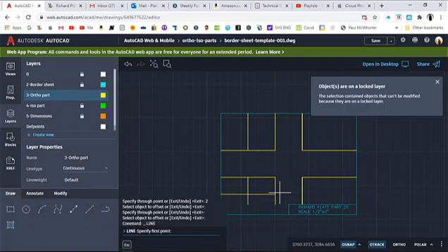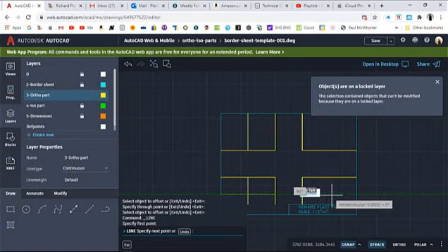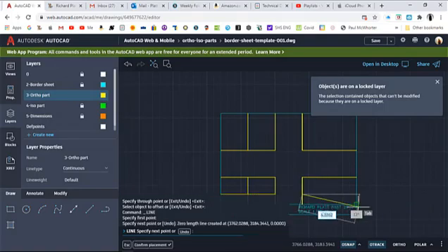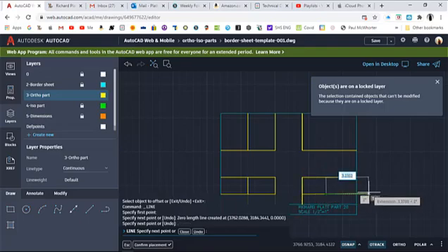And what we'll do is we'll snap onto the end of this line right here and just extend across just by touching it. And AutoCAD will then snap on the one to the other side over there, and we'll just draw a line out to here. Okay, and I'll make sure I stay on that plane. There we go. Okay, so there's that line there.